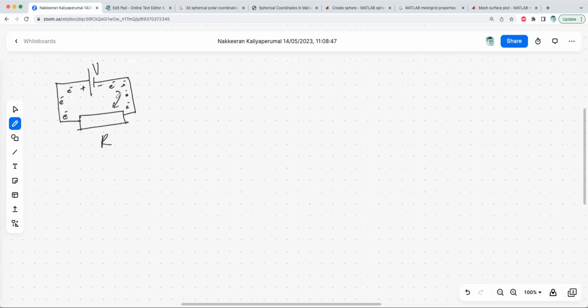Do you get that? We call that electronic current in this direction, but the conventional current is going to flow in this direction. Yes, uncle. As the voltage is time independent, we are saying that this is constant. Mathematically, we say that dV by dt is equal to 0. So when this is constant, the current I will also be constant, that is dI by dt will be 0.